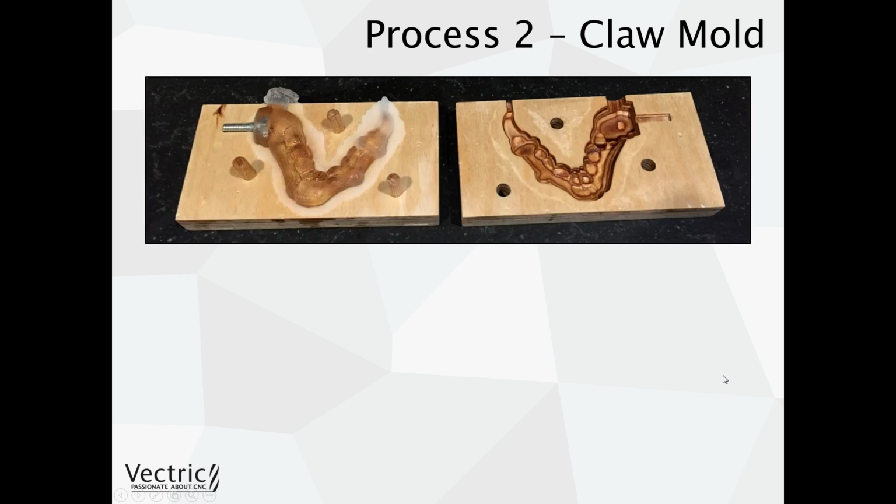Once we open the mold, we can see something like we've got here. Now I found after I'd made one of these that if I wanted to open the mold before the material cured and became its white colour, it helped to put petroleum jelly onto it for releasing the part. So I'll just smear the petroleum jelly around the mold here, and that would help me to prise it apart more quickly rather than having to wait until the material had cured.